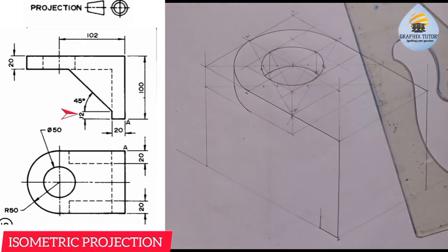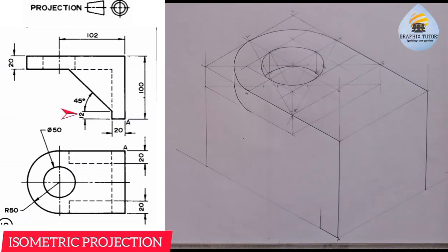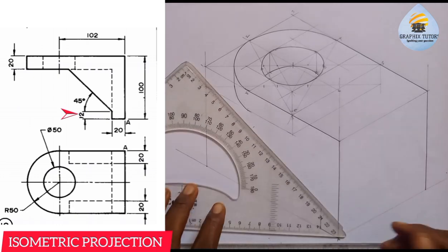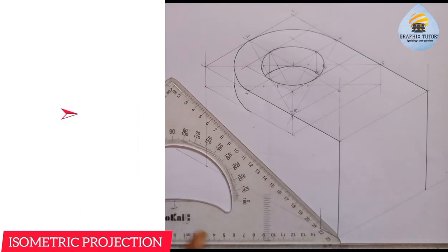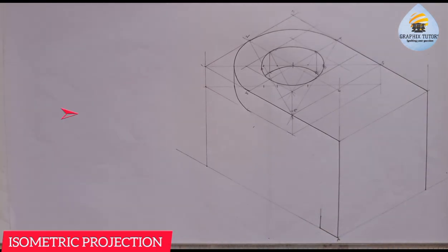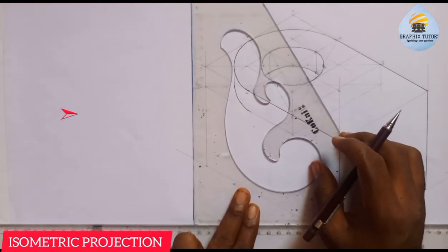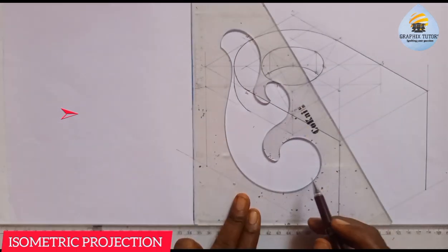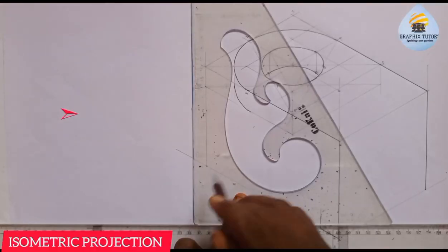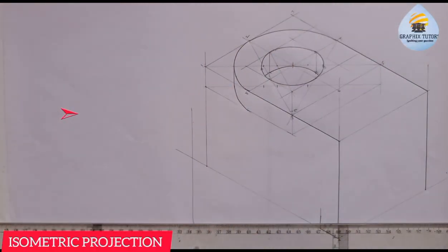Now this is inclined at an angle of what? 45 degrees. So you cannot use your normal set square and say you want to draw an angle of 45 degrees. It doesn't work that way. So what you simply do is you're going to redraw this. Let me just do it here so it's what I'm talking about. At this point, draw a vertical line downward this way. Can you see that? And draw a horizontal line this way.